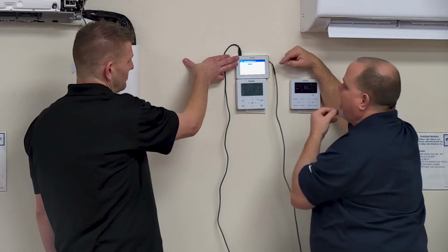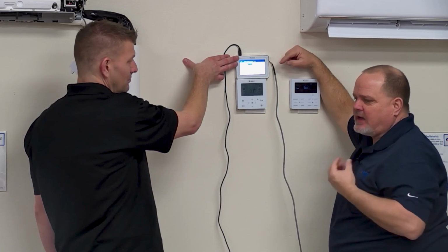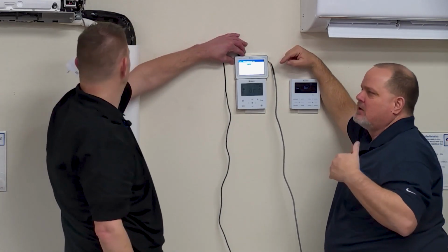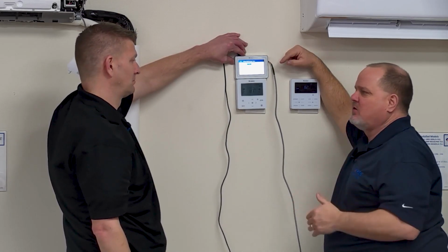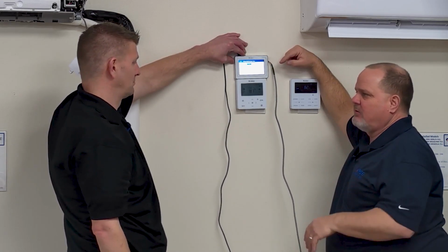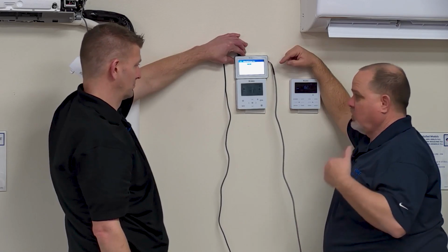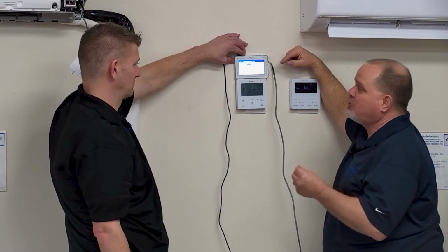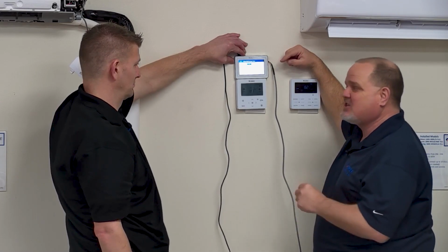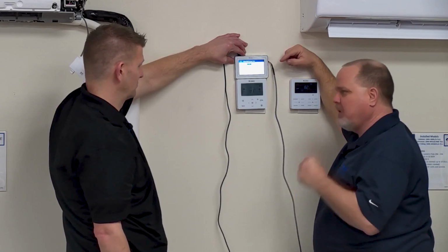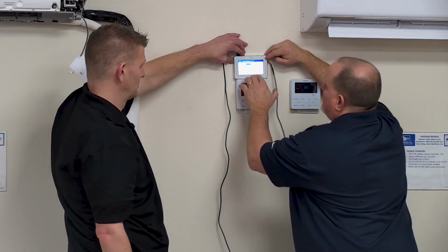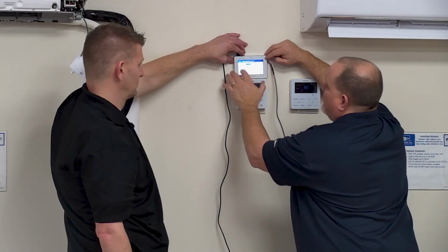I always say, to me, it's a lot easier to do refrigerant diagnostics in cooling mode. These machines will run in cooling mode all the way down to 0 with no problems. So when in doubt, check it out. Run it in cooling mode. That may make the refrigerant diagnostics easier for you. Good point. So anyway, that's a good differential.